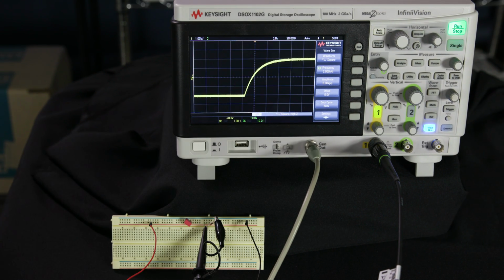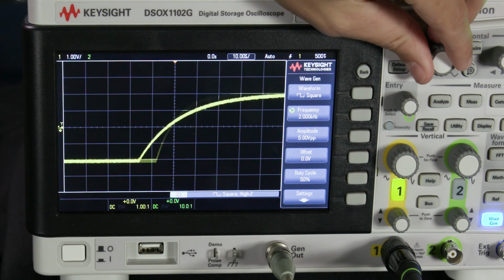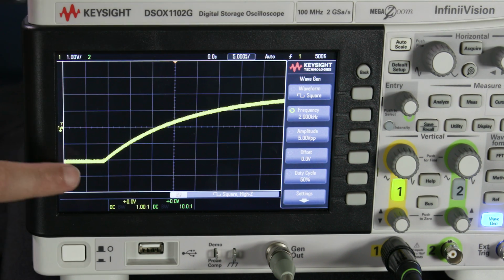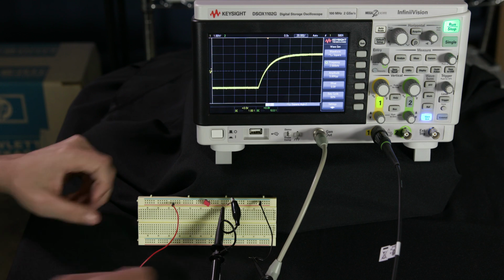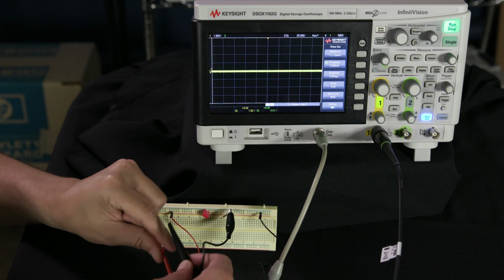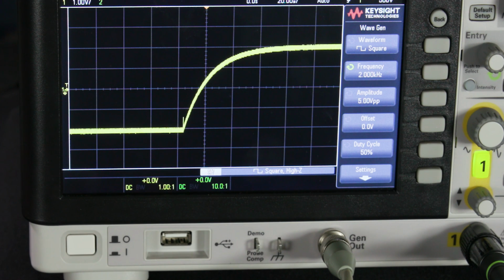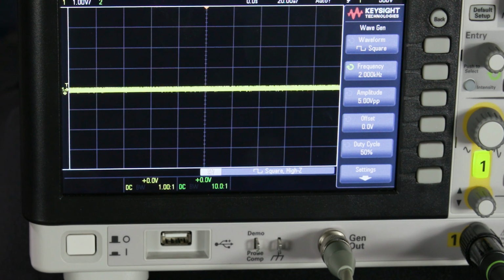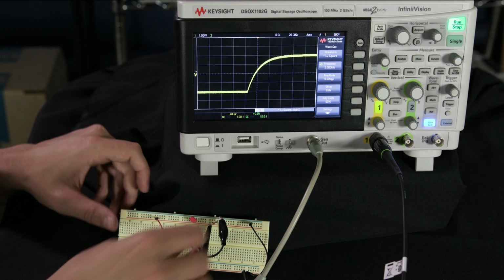And you can see when I'm measuring just my resistor, I'm not getting that spike anymore. Even if I zoom in, you can see there's a tiny little spike, but that's really not much of anything at all compared to the spike that we're seeing when I connect to this. So you can see the difference when I'm connected here versus connected to the resistor. So that was our clue that the wires were causing the inductance.